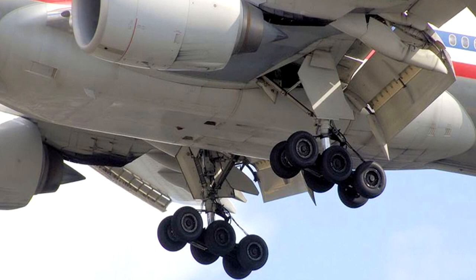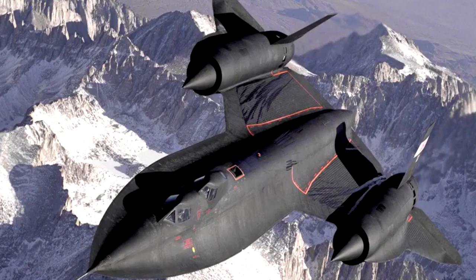Steel and its alloys are relatively heavy, but can be made very strong. They are used only where strength is vital and weight can be ignored, for instance, in undercarriage units. Titanium is much lighter than steel, but it is just as strong and can be used where fire protection is required, for instance in engine firewalls. Titanium has good strength, and it retains this strength and its corrosion resistance up to temperatures of 400 degrees Celsius. It is, however, expensive to produce.